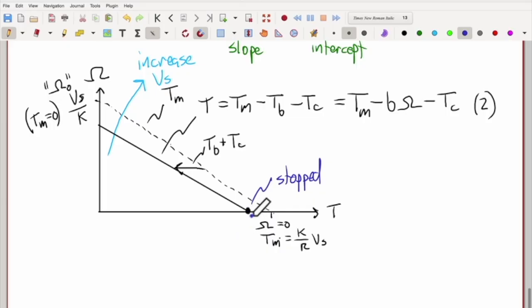And this is actually the maximum torque you can get here. This is the max torque. It's called stall, and it's called TS, stall torque. So that's the max torque at zero velocity. Then imagine you let go of the motor, and you start letting it spin. Maybe you're somewhere here, apply some friction.